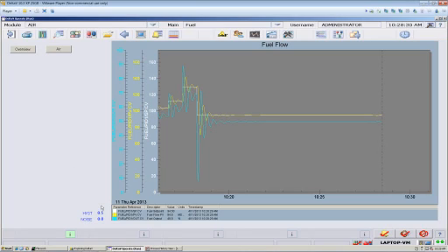It's a little harder than this in real life. I'm going to introduce some hysteresis in my valve. And by hysteresis, I mean sloppiness. We tell the valve to move, and there's something mechanically going on there. The valve body doesn't go to where we commanded it. I'm going to say the degree of that sloppiness is 3%. Now, you wouldn't do that intentionally to a valve, and you certainly can't do it by clicking a button in the simulator. But I just want to use the process to illustrate.